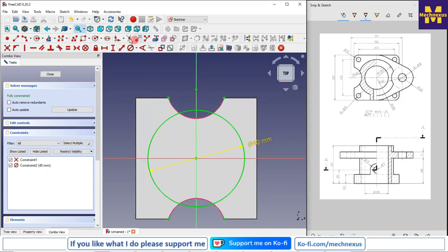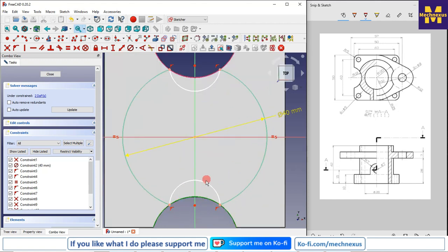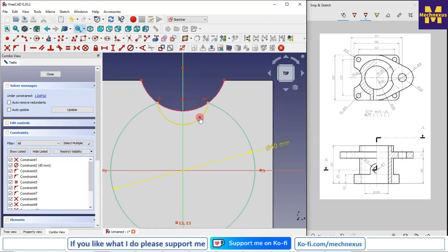Now I will trim the geometry, this one and this one, and I will select the 3-point arc. I will draw the two arcs on both sides, and now I will make them equal, this one and this one.